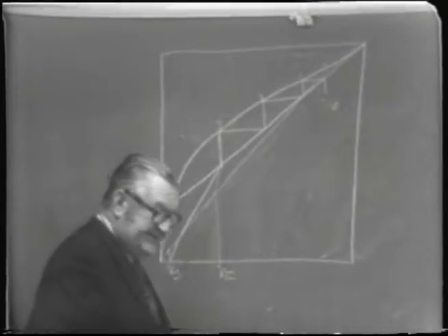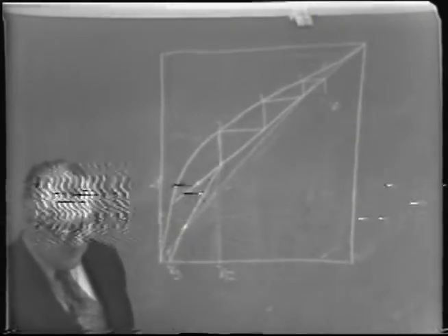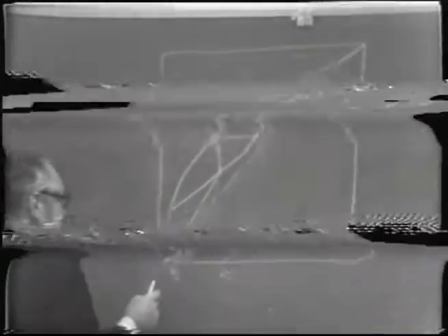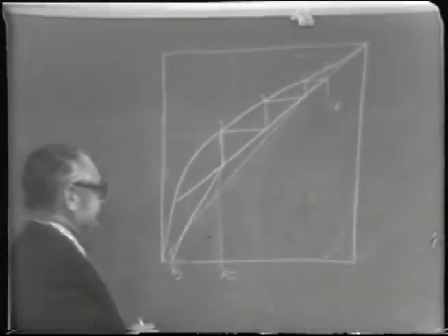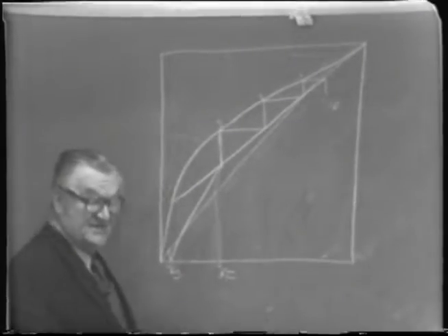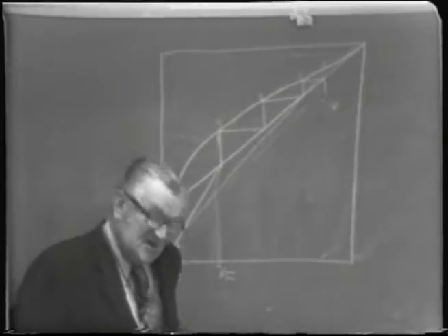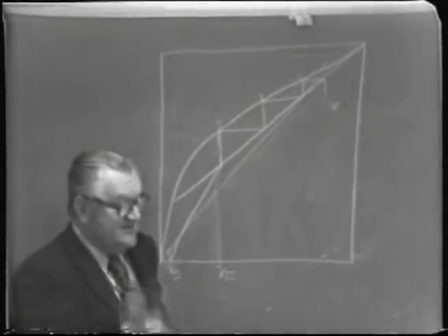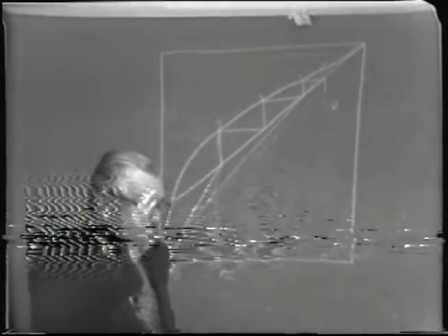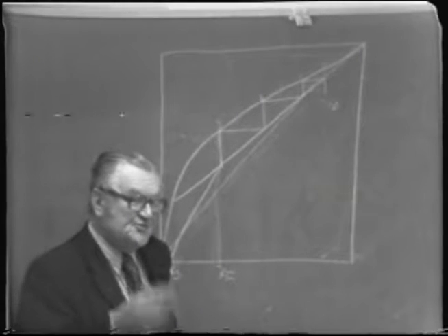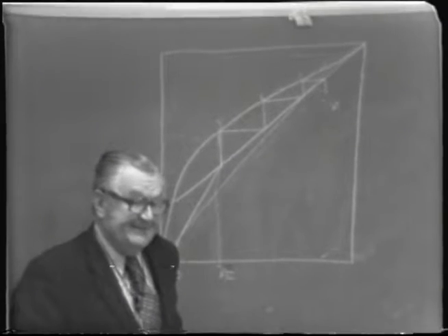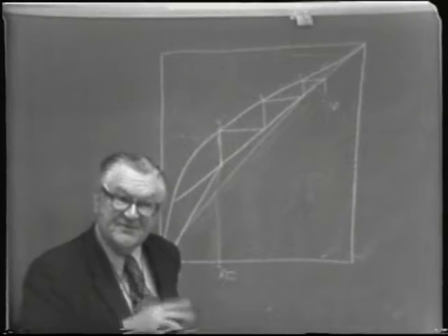But in reality, we're operating a system which, in effect, has, let's say, about 7 ideal trays in actual operation. Well, if those trays are there, they're going to be functioning. There's going to be vapor-liquid interaction on those real trays, and a certain amount of separation will occur.